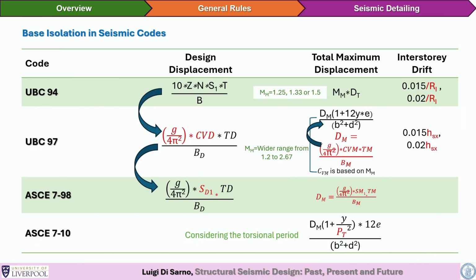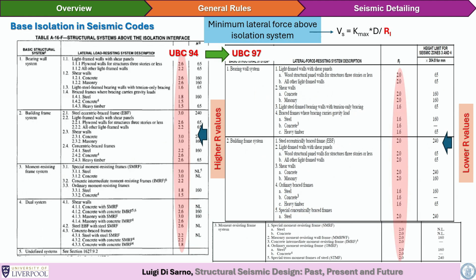So moving on, again, this is part of the base isolation seismic code. As Tony said before, everything is available for free on the internet, but this is just a matter of comparing them, which means that the philosophy around the world is pretty much the same. So it doesn't matter which code you're using. They use pretty much the same approach. It's important about the technology. And since 1997, base isolation has been introduced in ASCE, chapter 12, then it moved to chapter 11, moving back and forth, depending on if it is classified under passive devices or more generally explicitly as base isolation. But it has been proved a very effective type of solution for retrofitting structures or for new buildings.